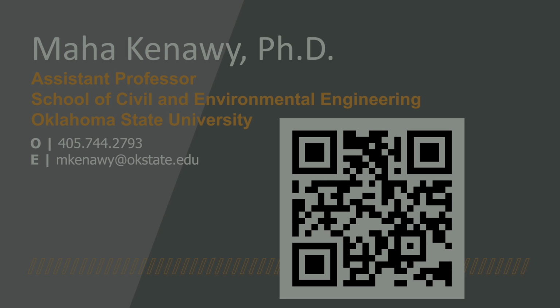As you looked at this, do you understand exactly what parameters in the Graves and Pitarka rupture model control the rise times for displacement? Because that's a critical value. No, I can't say that I do. I think what we looked at was how the slip patches influence those fling displacements. It would be interesting to understand what exactly controls that rise time. Because you can imagine the base of the building is moving over very rapidly, and how rapidly matters, right? So just understanding how that relates.